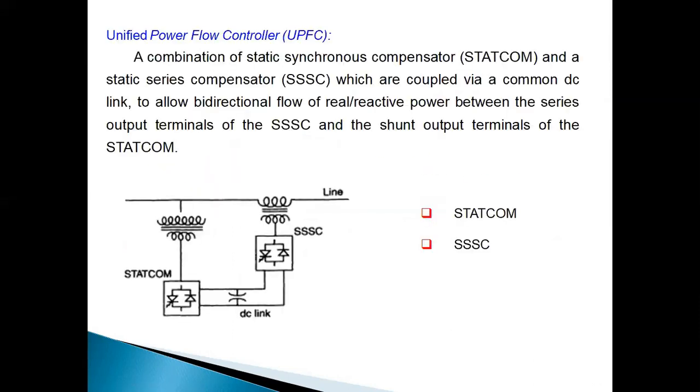Now the next and last one is UPFC. With this I will close. STATCOM I have completed, and UPFC I am going to discuss now. Unified Power Flow Controller. We have got two converters. One is STATCOM, another one SSC, connected through a DC link. Already we have seen the concept of SSC and STATCOM. STATCOM I have explained in detail. SSC I have given only a brief explanation.